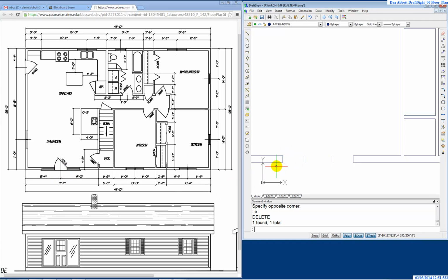Now I can go ahead and draw in a window and a raised sill. And that window and the raised sill are just going to be drawn with individual lines. If you take a look, it's a pretty simplified system. So I can actually take this, bring it to here, this line, bring it to here. Now I'm going to draw a line that goes down the middle. So I'm going to go to the midpoint to the midpoint, midpoint to the midpoint, and that symbol is good enough for what we're doing. In fact, if I look at it, I guess I can bring this in as well. I didn't really need to trim that out quite so far.